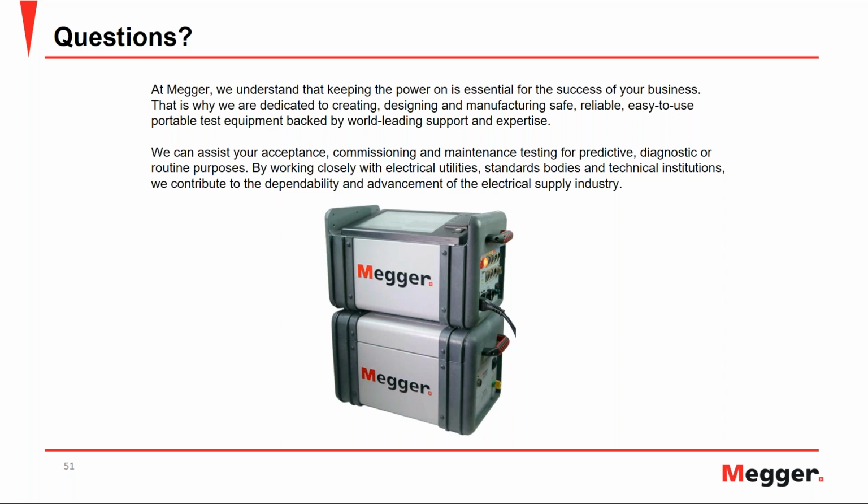Sure. So ITC essentially creates a relation between frequency and temperature based on your dissipation factor. And that's why it's necessary to perform your narrowband dielectric frequency response in order to provide you with the correct ITC, because you need that frequency sweep to be able to generate the relation into temperature. And the way that's done is through the Arrhenius equation. And that's the equation that was shown on the slide.